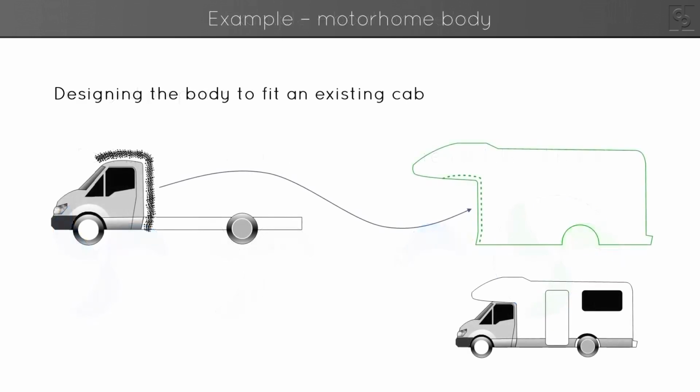With the motorhome, you're going to make one expensive mold to build those bodies to fit the truck cabs. They're mass-produced and you have no control over the build tolerance, and you can be sure they won't all be exactly the same. They could be 10 millimeters different from one example to the next. So you scan the cab you have got, model it as you think it was intended, with the cab central on the truck chassis, and then you offset the cab surface by an amount that you can confidently fill with gap-filling sealant.